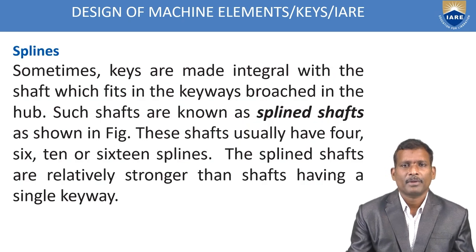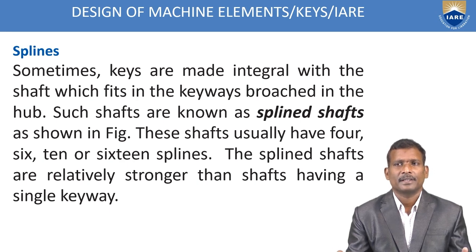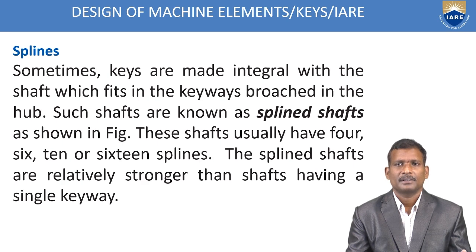Next one is splines. Sometimes keys are made integral with the shaft, which fit into keyways broached in the hub. Such shafts are called spline shafts.